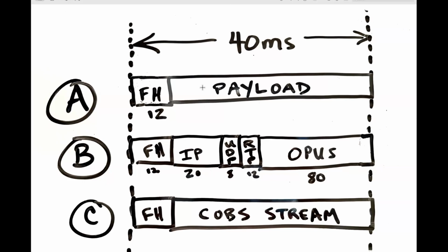And this is a replacement for the older, more primitive kind of byte stuffing that you may have run into before in protocols like SLIP or the KISS TNC for packet radio, where they stuff in bytes wherever they see something that they can't handle as binary. This is a smarter protocol. It only adds a tiny bit of overhead and it never grows to a large amount. Whereas with SLIP, you can have up to 100% overhead. This tops out at a percent or two and is always consistent and very simple.